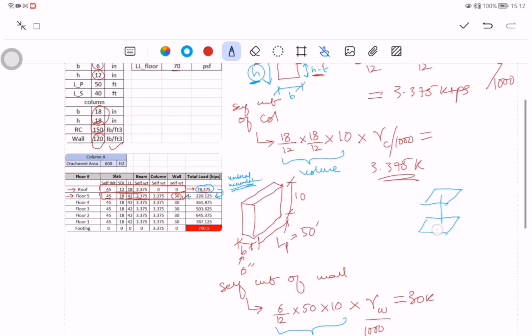First of all, at roof level we calculate from the catchment to the column, and then at floor 5, the catchment to the column along with this load on the column, because this is the baggage it is carrying, the catchment of the previous floor. Similarly, at floor 4, the catchment to the column plus the previous catchment load will be transferred to this column.